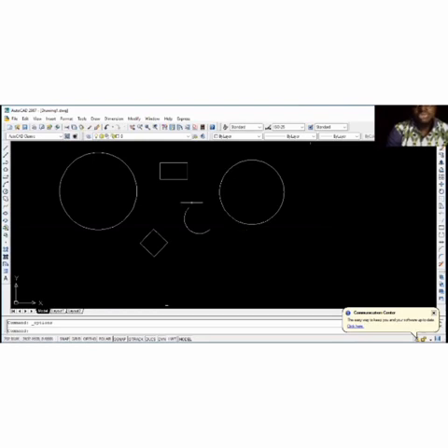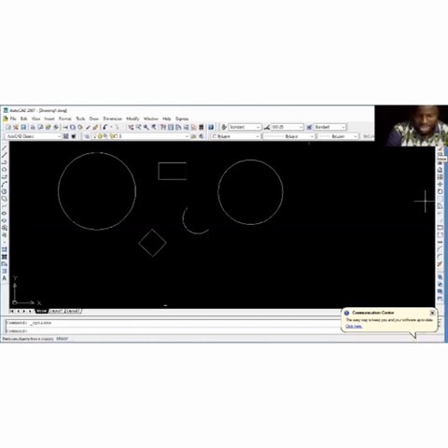Now, if you want to erase objects in AutoCAD, we have three methods. So now these are different objects you want to erase. So you may want to erase this. The first method, you can select the erase command. You know your erase command is under your modify toolbar. This is it here. You can select it first and then select the object.